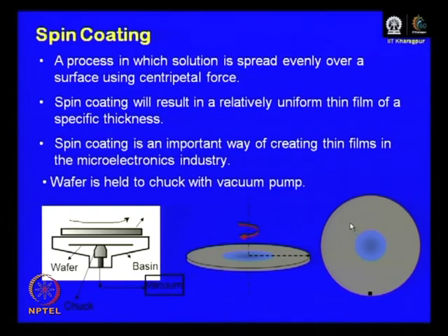You may dispense it in a fashion that during dispensing itself the photoresist solution covers the entire wafer, or you can dispense it at some location centrally, it really does not matter. If you are working with a very small piece, maybe you would like to cover the whole substrate during the dispensing step itself. But as you dispense and turn on the rotation, due to the centripetal force, the liquid meniscus starts spreading. This is not exactly what you worry about in commercial photolithography, but from the standpoint of spin coating, I may want to point out something here.